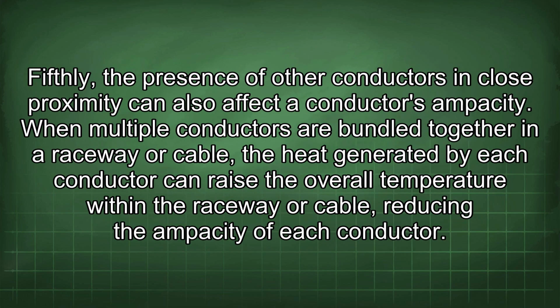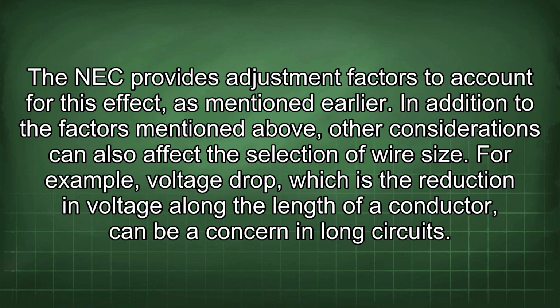Fifthly, the presence of other conductors in close proximity can also affect a conductor's ampacity. When multiple conductors are bundled together in a raceway or cable, the heat generated by each conductor can raise the overall temperature within the raceway or cable, reducing the ampacity of each conductor. The NEC provides adjustment factors to account for this effect, as mentioned earlier.